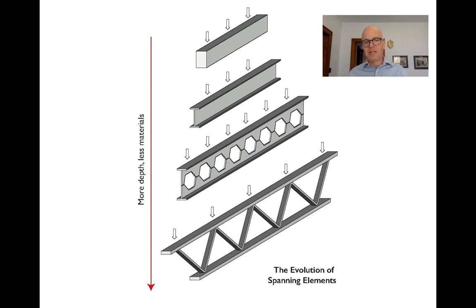And the chords in between that form the triangular panels of a truss, these are basically doing the work of a web in a beam. They're providing, if you think about it this way, shear resistance to the two flanges, locking them in place relative to one another.